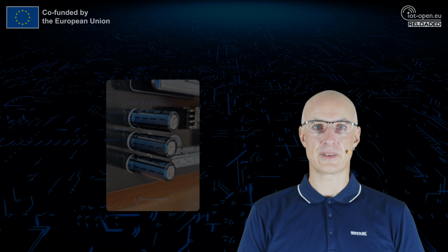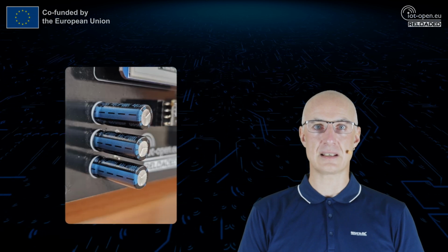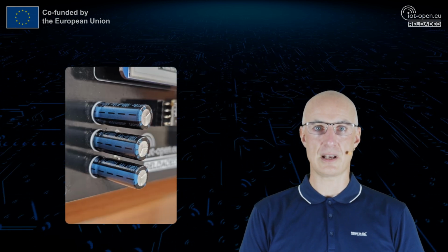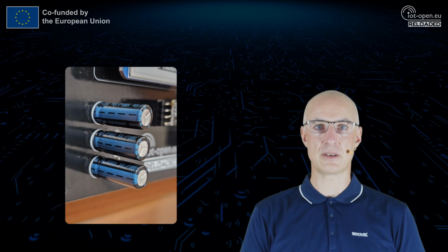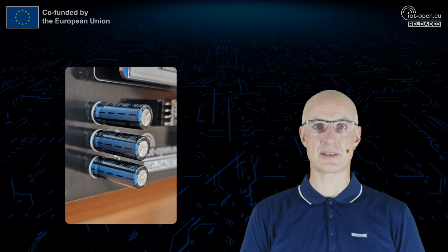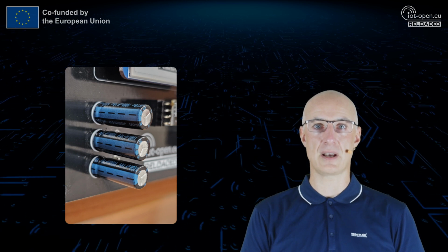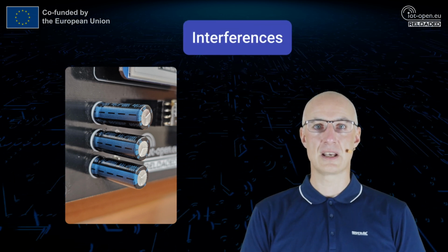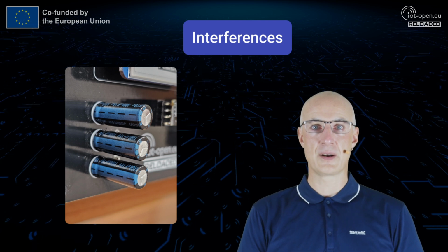Proper filtering of the current interferences is essential to ensure stable MCU operation. Even when using good quality power sources, nearby communication wires, power wires, and electromagnetic fields generated by actuators can cause severe voltage interference, making it rise and drop.